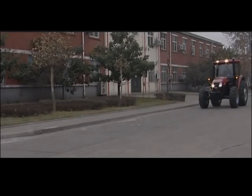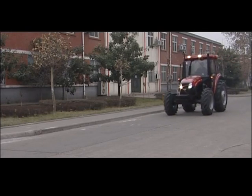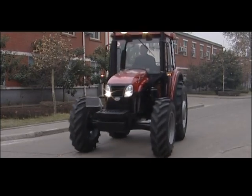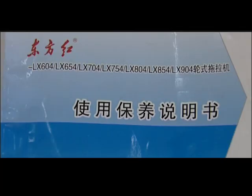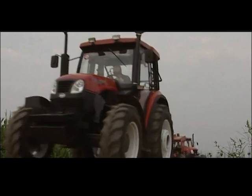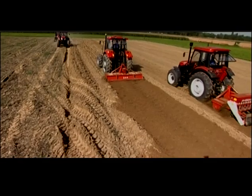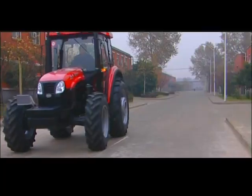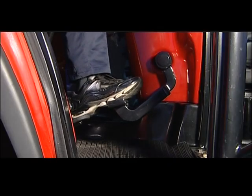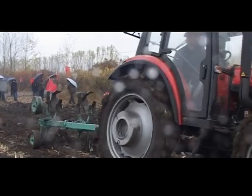Tractor idle drive and running in with load. The running in for tractor can be done only when the technical status for all parts running in are in normal conditions, following the running in procedures and time sequence as the tables and figures in the manual. After the idle drive running in, when the tractor technical status is completely normal, the laden running in can be done. During the idle drive running in, steer to the left and right and properly use the brake.